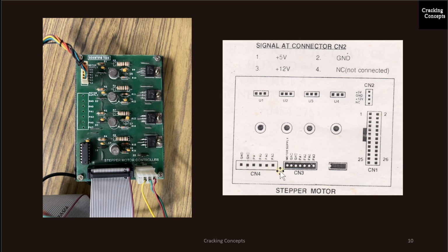So here we have 6 connections, 2 grounds, and then we have PA1, PA2, PA0 and PA3. These values were the ones we derived in the tables when we saw the working of a stepper motor. Now the other end of this cable is connected to the motor, through which these values are communicated for its stepwise rotation.